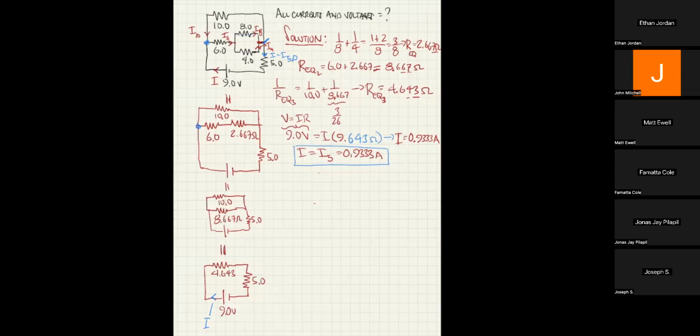Yeah. And why is I10 going down? I wanted to show you that it doesn't matter if we accidentally choose what we think is the wrong direction. What we're probably going to find is, in fact, that this side of the resistor is a high voltage and this side is low. But one of the problems is when you're solving these problems, you actually have to put down a direction for each of the currents.